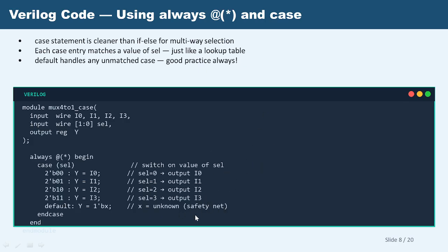So this default case is called a safety net. Unknown value has occurred. So you can say that something is passing there as an input, so our code has broken, okay. Just to make sure where our error is and why the error is coming, to check that you are going to give a default case using the case statement, okay. So this is how you are going to design a 4:1 mux using the case statement, okay.